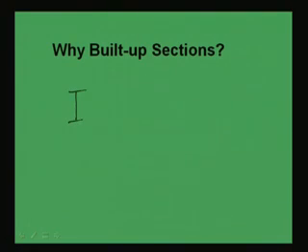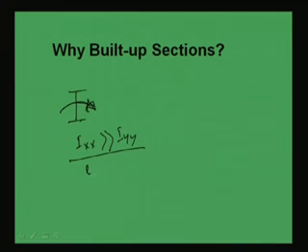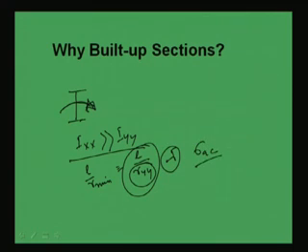Suppose I have an I section, say this. Here if the moment is coming in this way, it will easily buckle, because Ixx is greater than Iyy. That is why the slenderness ratio L by r minimum will be L by ryy, and as ryy is less, lambda will become more, meaning the allowable compressive stress sigma ac will be less. So we have to see that equal resistance comes from both sides. Whatever resistance is coming from the XX direction should come from the YY direction also.